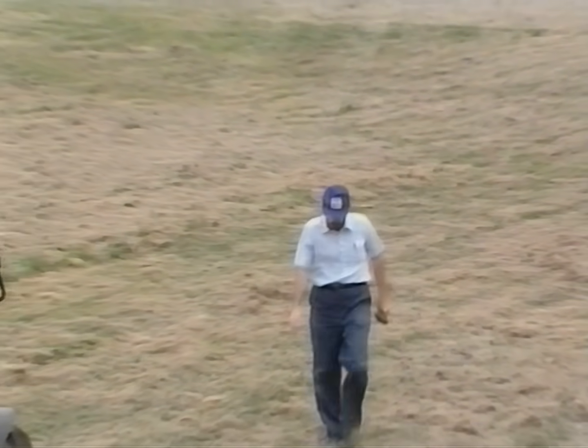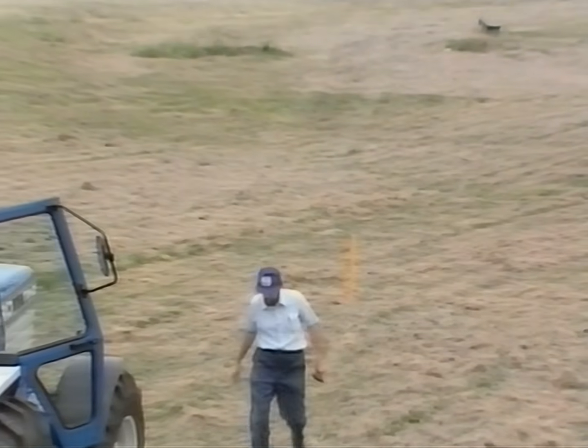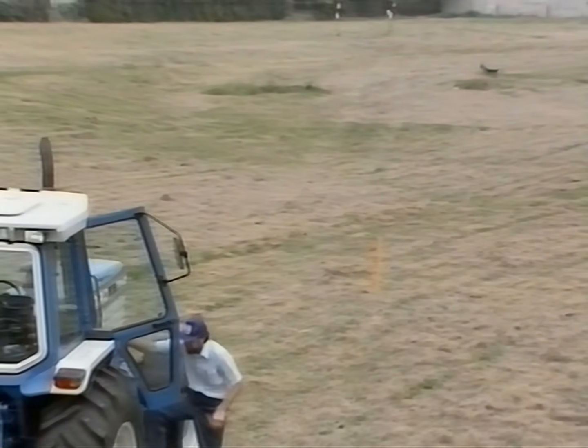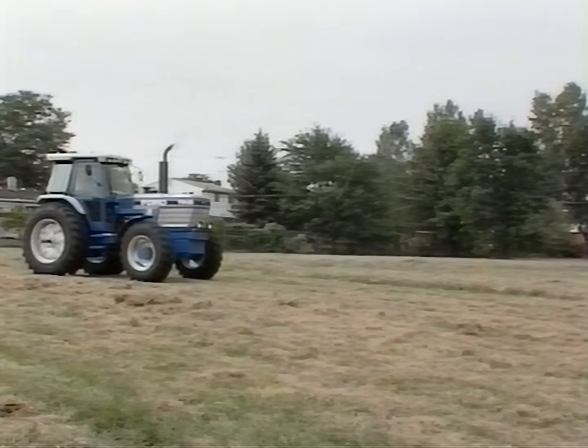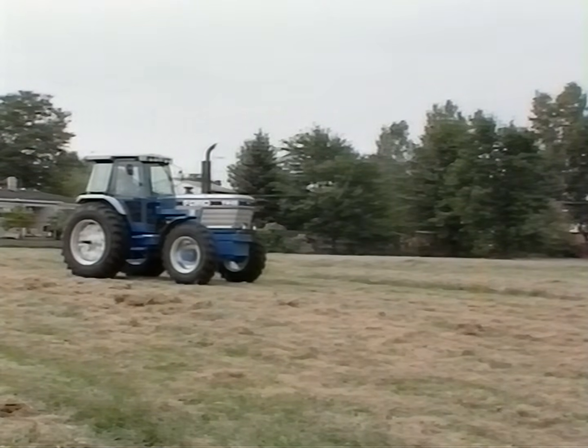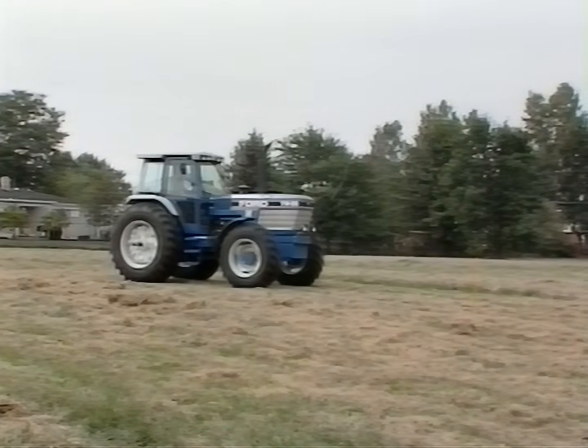In order for the performance monitor's distance calibration to be accurate, it's important that the start and finish are marked accurately. Next, drive the tractor toward the start of the course at approximately 5 miles per hour. Press the on/off switch when passing the start marker and maintain the slow, steady speed over the course. 3 dashes should now be displayed on the TPM screen.